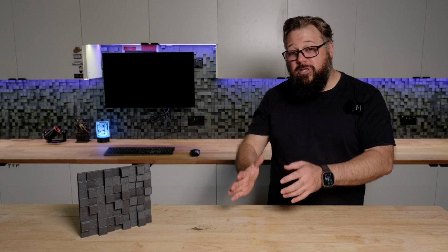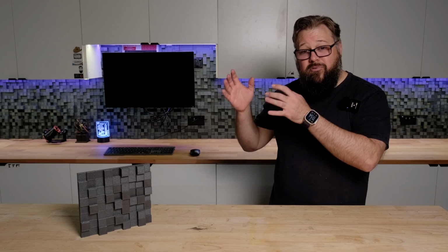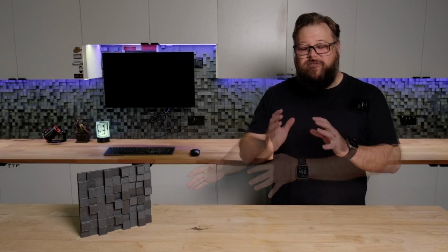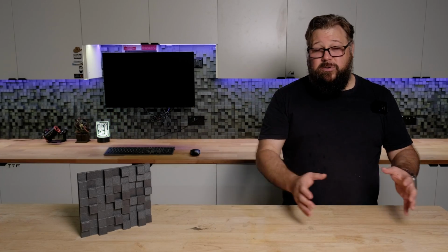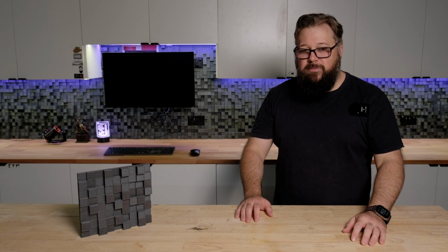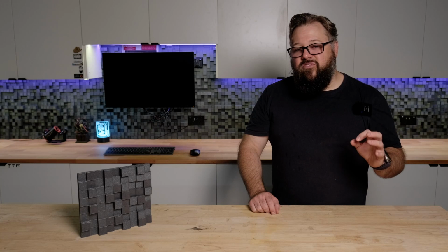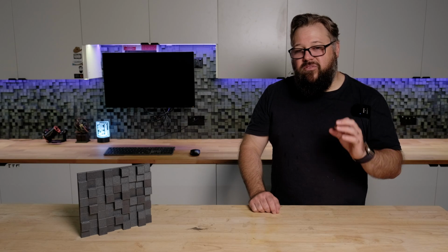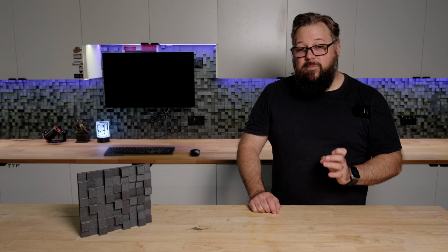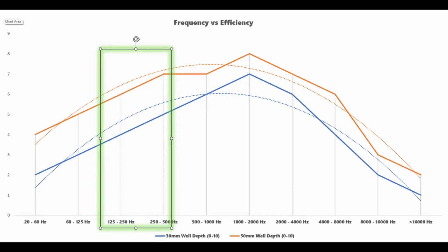I had to make a conscious design choice on the well depth to keep it practical on a 3D printer. Fortunately, the well depths tend to have diminishing returns and they are well within the realm of possibility for practical 3D printing. 30 millimeters is decent, 50 millimeters is great. The 5 through 50 millimeters has an improved frequency response, but both should actually perform quite decently in the frequency ranges that human voices tend to fall into.